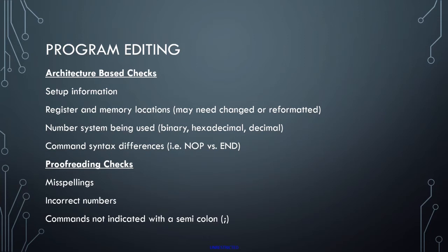You should also pay attention to the number system being used. So other systems may require formatting in different number systems. Also look at the command syntax differences. So a couple weeks ago when we looked at our end command, we saw that we use the END to end our program, but sometimes in some architectures or some systems, NOP is also used to end the program. Sometimes those are interchangeable and sometimes they're not. So that's something to look out for. Commands may vary just a little bit in how they're written.